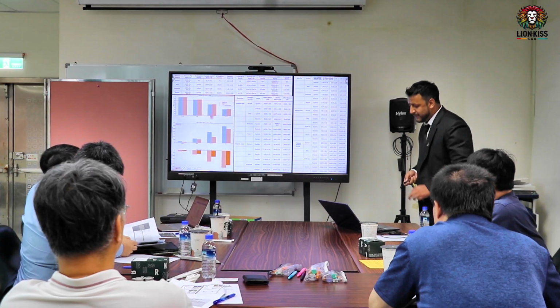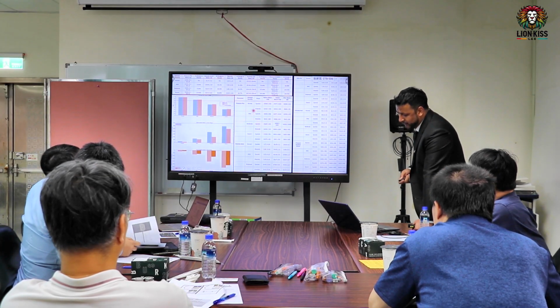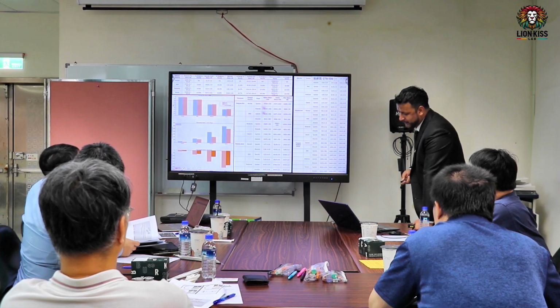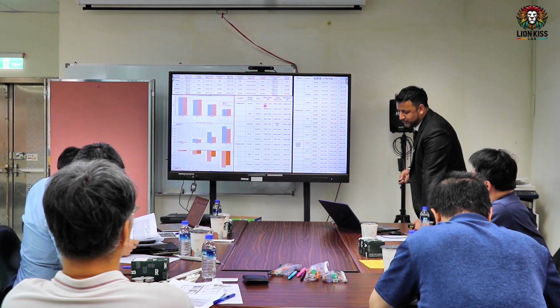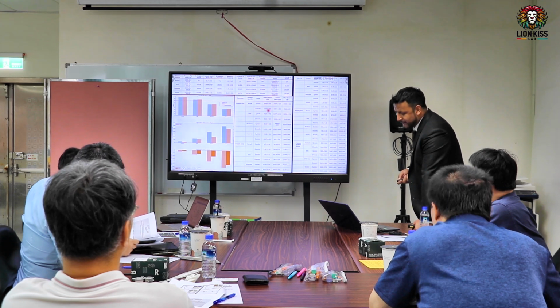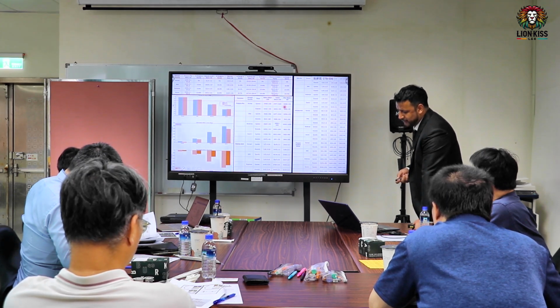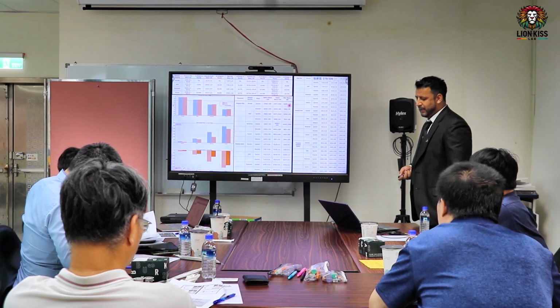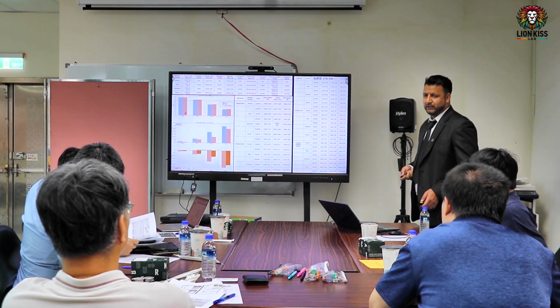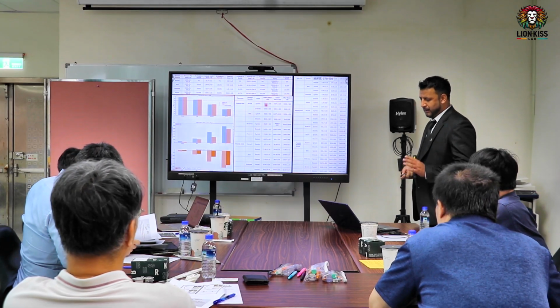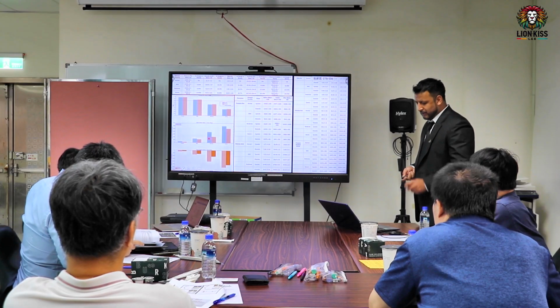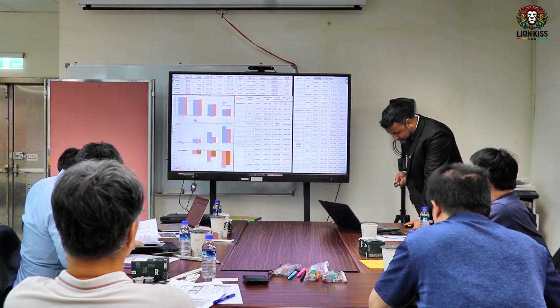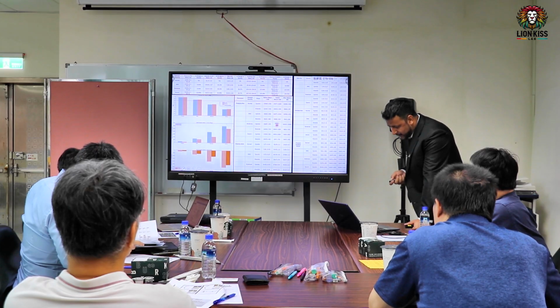So after that we measure the pressure for normal, mild, moderate, and severe cases at systolic and diastolic, before the stenosis, at the center of the stenosis, and after the stenosis. With the before and after values we can get the FFR value, and with before stenosis and center we can get the pressure gradients and wall shear stress gradients, and from center and after we get the negative wall shear stress gradient.